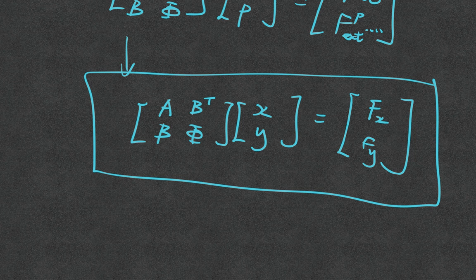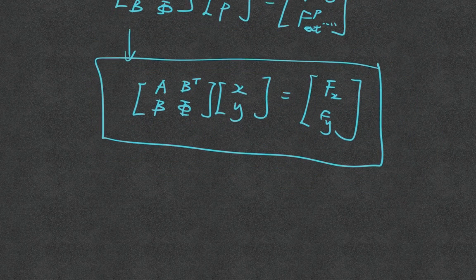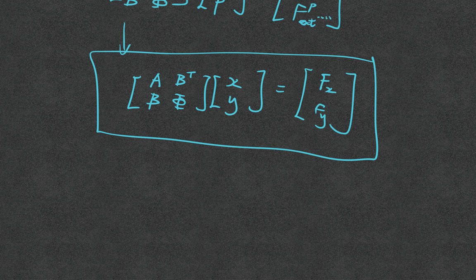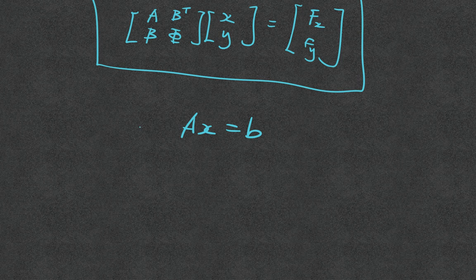In your undergraduate course or in your finite element course, most of the problems are single variable boundary value problems. So what you want to solve is AX equals B after you linearize, okay? Even though you have nonlinear mechanics, if you're linearizing it incrementally, you actually need this linear solver.